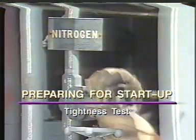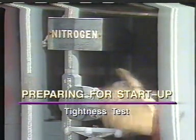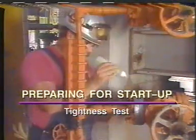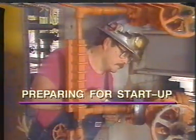A tightness test is usually performed by running pressurized steam or nitrogen into the tower. A pressure buildup indicates there are no leaks. If the pressure continually bleeds off, there is a leak somewhere in the system.